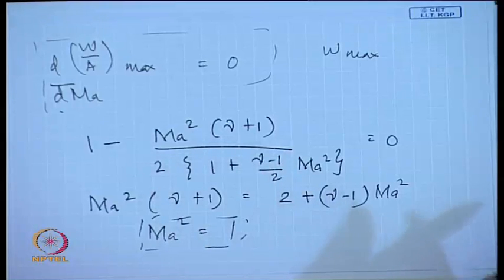So, therefore, we were talking about the choked flow conditions, or rather we were talking about dA equals to 0, when dA equals to 0, Ma equals to 1 and so on and so forth, and we find why Ma equal to 1 is so very important, because that gives us the maximum flow rate from the converging nozzle under the present circumstances. Okay. So, therefore, we find that for Mach number equal to 1, we get the maximum flow rate under the present circumstances.